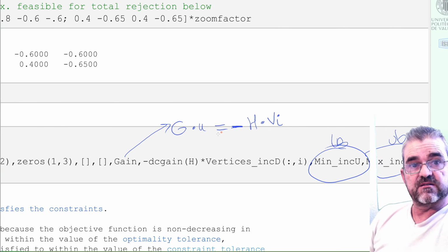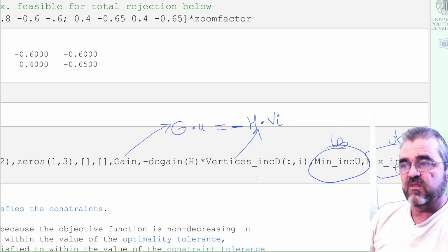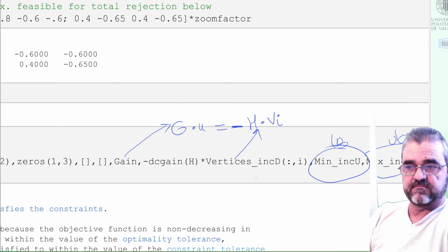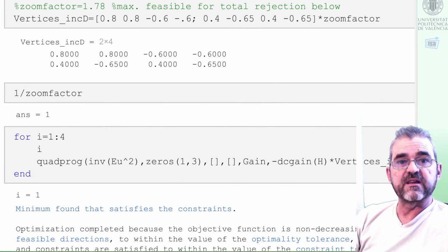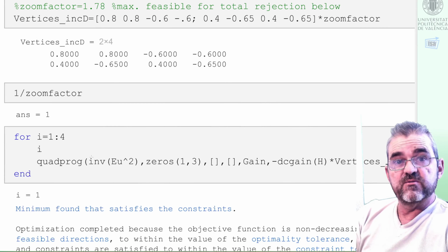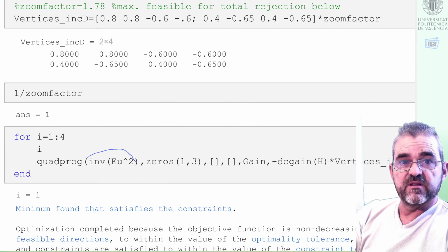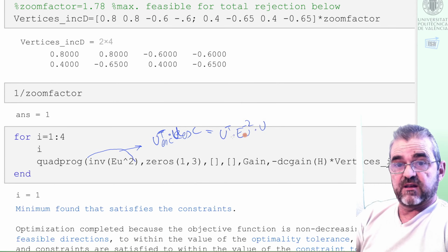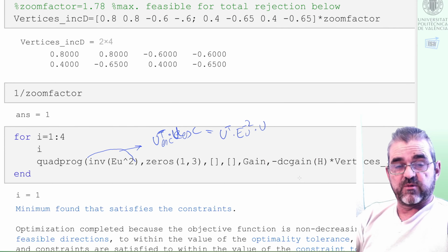So if I can cancel extreme disturbances without saturation, I will be able to cancel non-extreme ones also without saturation. So these are the equality constraints, and then I can minimize whatever I wish. But for the numerical results to coincide with the pseudo-inverse scaled results we got in the SVD, I am minimizing the square of U scaled, which is of course this thing in absolute units, because gain G and H have been put in absolute units, as well as input lower and upper bounds.